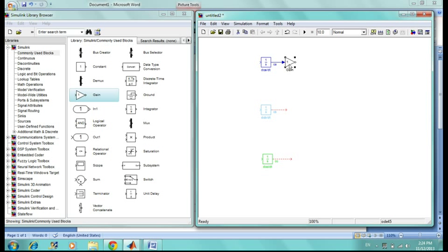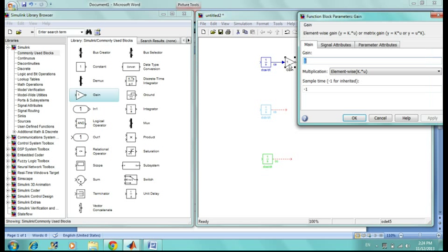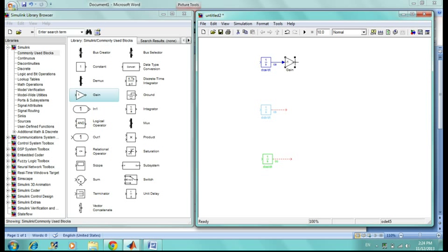Okay, and to change the constant that you're going to multiply, just double click on the gain block, write -1, since the value of k1 is just 1, so just -1, and then apply. Okay, now the product from that multiplication will be minus ca, which is minus k1 ca. So just double click on that, you will get minus ca.